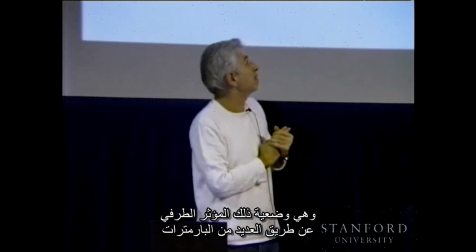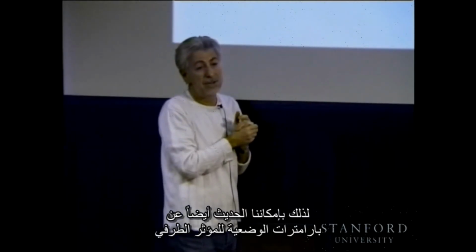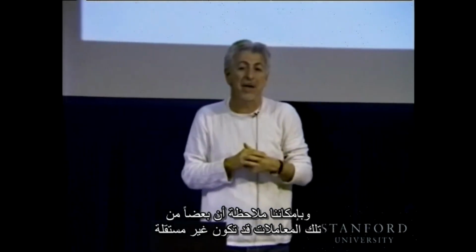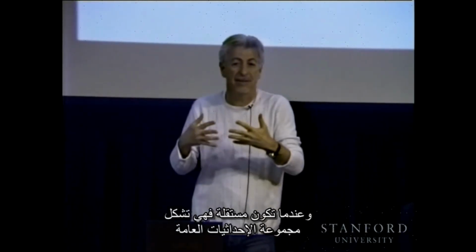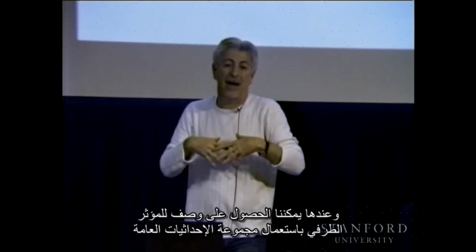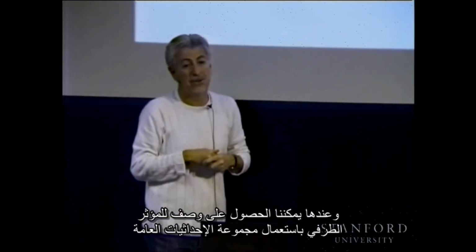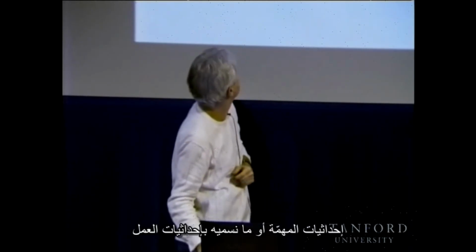parameters. So we can talk also about configuration parameters for the end effector, and we can see that some of those parameters can be dependent, and when they are independent, they form a set of generalized coordinates, and then we can have a description of the end effector using a set of generalized coordinates, task coordinates, or what we call operational coordinates.